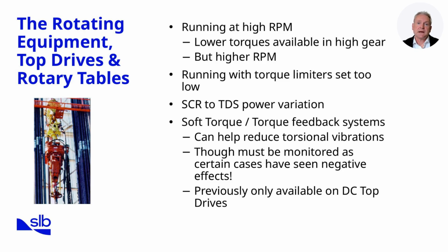The key takeaway is that equipment settings, RPM, torque limiters, and torque management systems directly affect vibration behavior. Optimizing these parameters ensures smoother operation. Next, we'll explore other operational factors that also contribute to vibration.